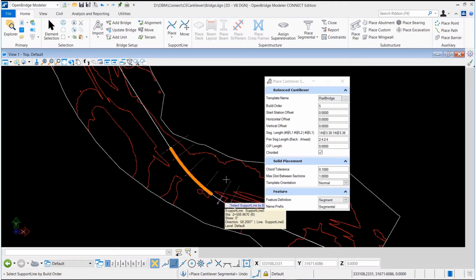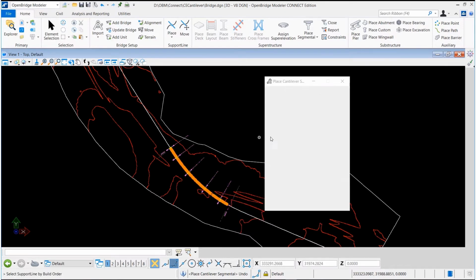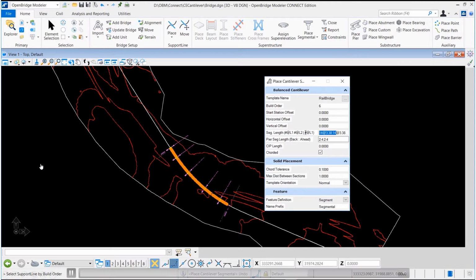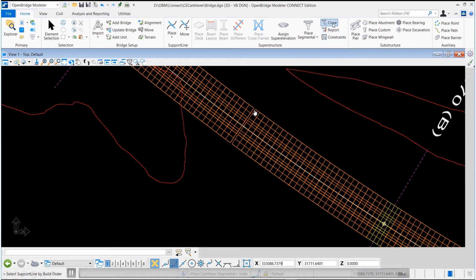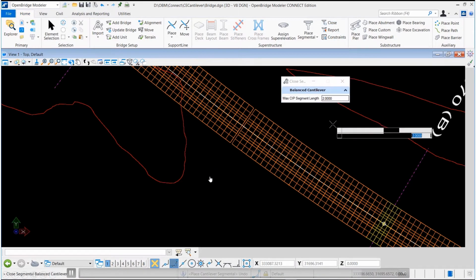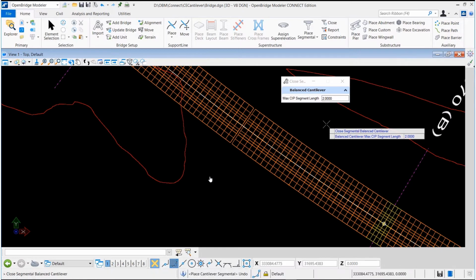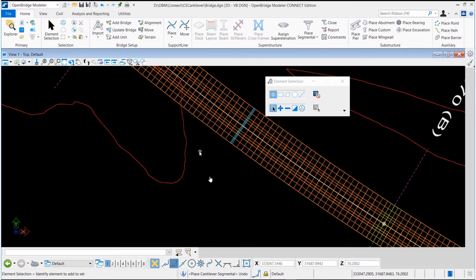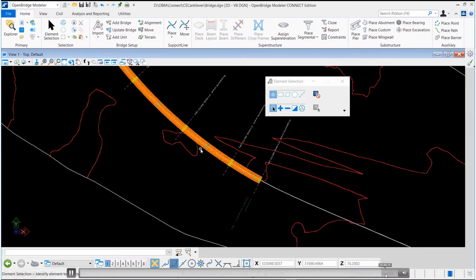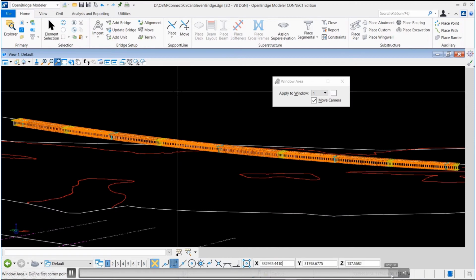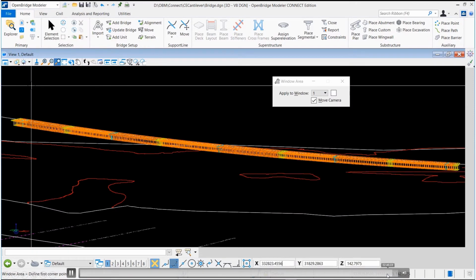So I continue with this process until I finish the complete bridge. And at the end, I just need to apply the closure pours that I need in the gaps, and I just have to select in each span how it's going to be closed until I have, of course, the complete bridge built up. And I have my bridge already.